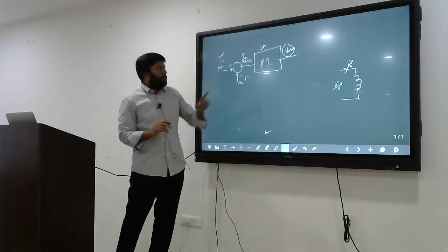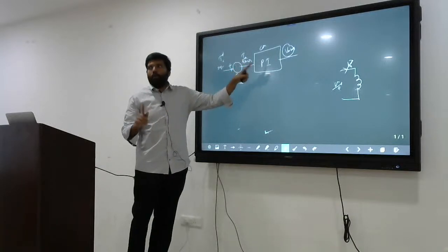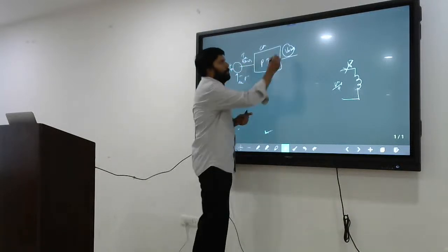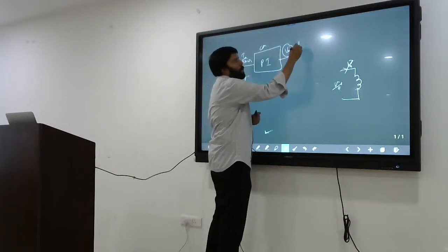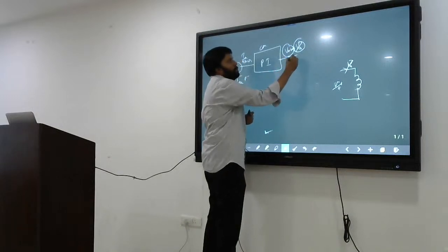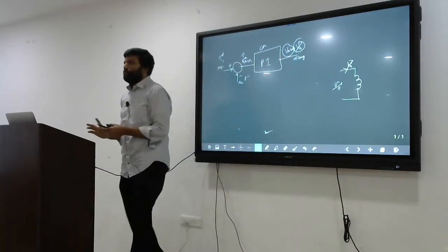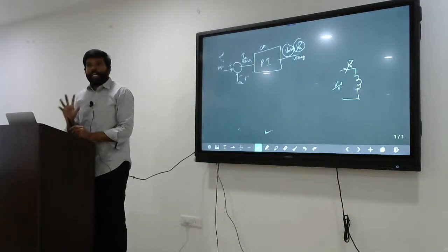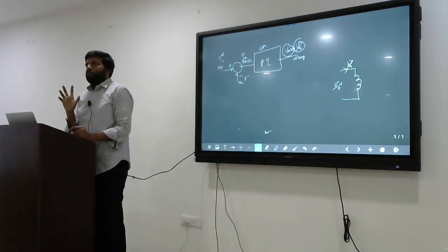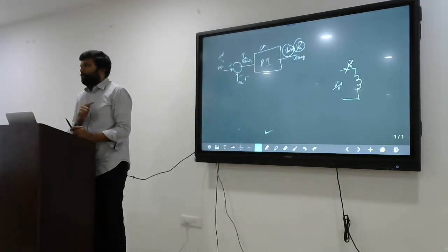But the problem is, this error we can control only by adjusting the Va. That's why the expected output of the controller is voltage. Voltage is the output. So your controller practically, please try to understand, this is called current controller. We are trying to rectify the current error.